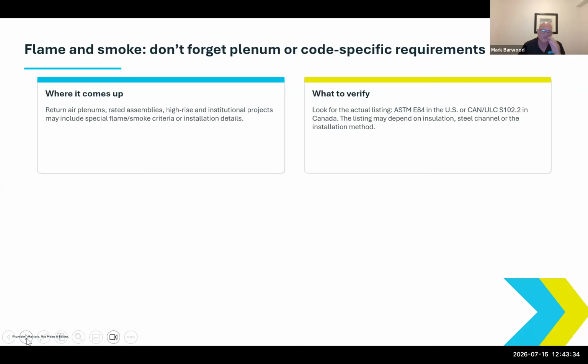Like I said, I was on a job site and there was PERT. The guy told me it was rated S101, S102, and I looked at their spec sheet. Sure enough, they had that approval, but in brackets they said, see the asterisk. I looked at the asterisk. It said pipe outside of the wall has to be insulated.